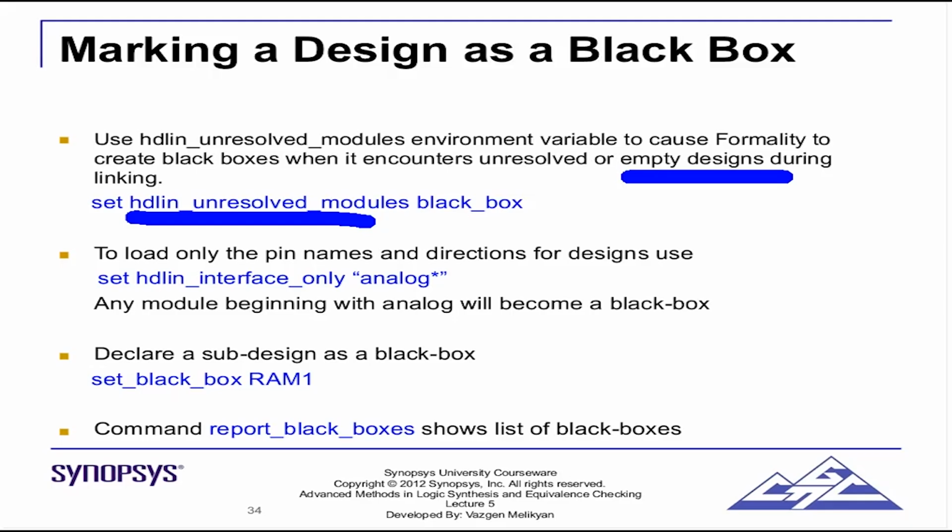The second thing you can do is use this command, set the variable, and set it to mark the cells which you want to be explicitly black box. Or you can use the command set black box. So there are multiple ways to set something as a black box.